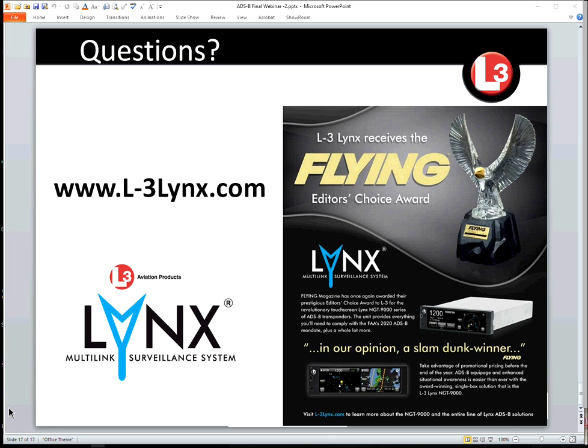What about interfaces with Garmin technology? So right now we will display traffic on just about every Garmin display out there that's post MX20, Garmin 430. Some of the really legacy stuff, they don't have the capability or processing power to display traffic. However, weather information right now will not be displayed on those devices. So right now you won't see the graphical weather or the METARs or TAFs displayed on those devices.